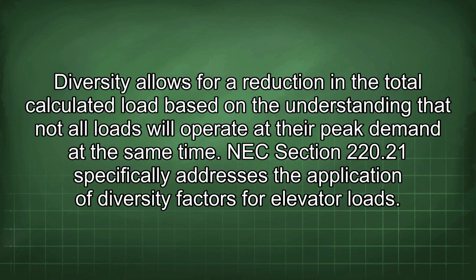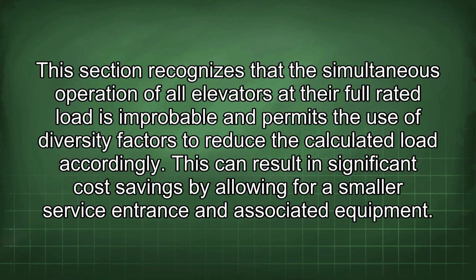NEC Section 220.21 specifically addresses the application of diversity factors for elevator loads. This section recognizes that the simultaneous operation of all elevators at their full rated load is improbable and permits the use of diversity factors to reduce the calculated load accordingly. This can result in significant cost savings by allowing for a smaller service entrance and associated equipment.